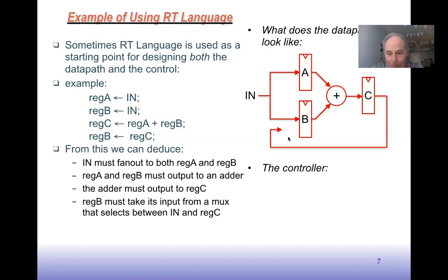And then we're kind of in trouble here because the input to B is already occupied. And of course, we know how to fix this. We put a multiplexer here. So in this clock cycle, we're going to choose from the feedback path. But on this clock cycle up here, we choose from the input. So we'll take that out and replace it with something that looks like this. So we have a multiplexer here and another control point.